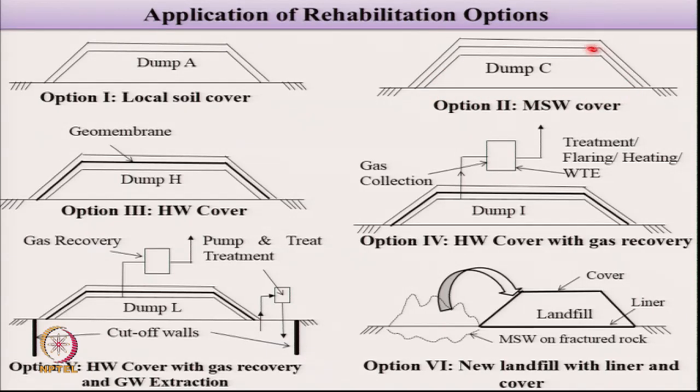As I said, you put a municipal solid waste cover if a liner exists at the bottom. So if you have natural clay at the bottom, then you will design it like a new landfill. So a municipal solid waste cover can be used. But do remember, gases will still come out because this is not designed for greenhouse gas emission control.